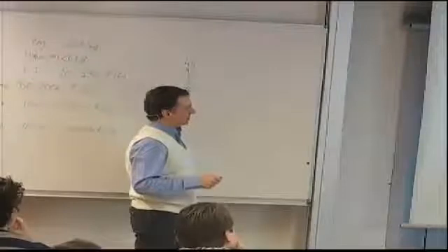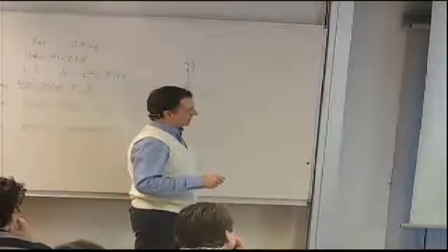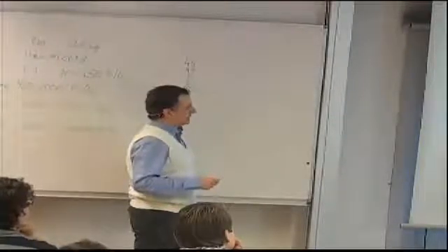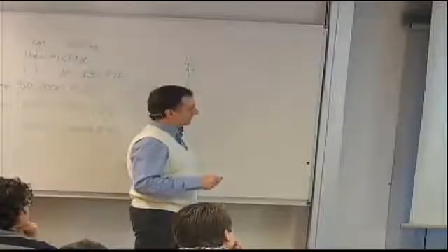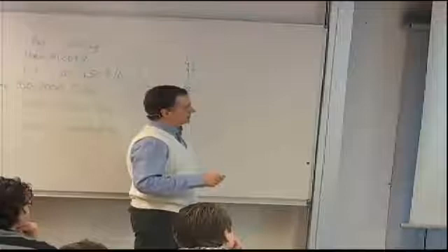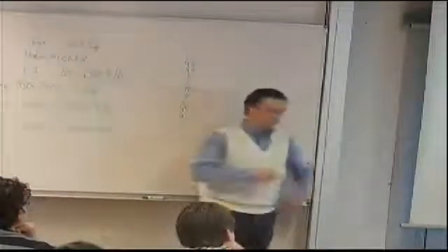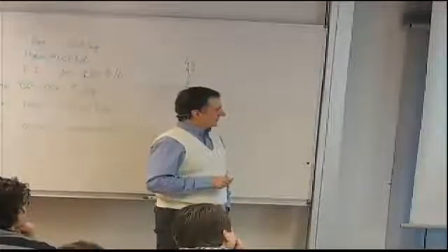Now if I take this and I substitute in my weight expression to replace the thickness, I get an expression for the weight which involves the density and the quantity force divided by width divided by the failure strength. And if I'm to compare graphite or carbon epoxy materials to aluminum, then the ratio of the weights would cancel out the applied force, which we assume to be the same, and would cancel out the width because we're having the same planar area, and we'll end up with a ratio of density to failure strength.